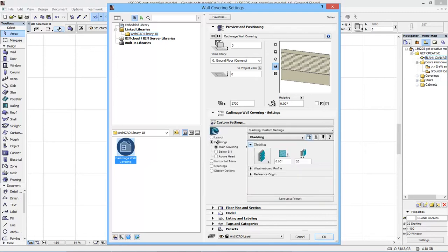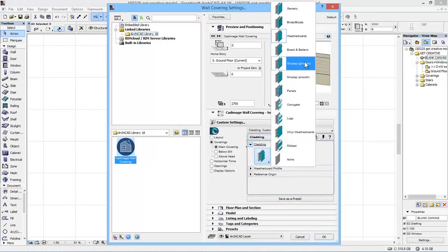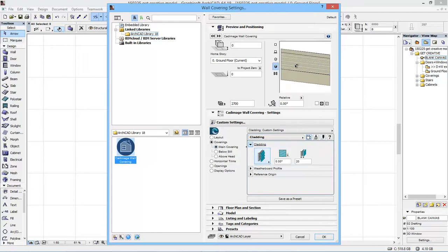If we then look at the coverings themselves, this now is split into 3 areas. There's also 2 settings in here. There's the cladding, and then there's the vertical trims we can apply with it. So we'll take the main covering first, and I think what we'll have with that is a little bit of grooved shiplap. This then has an option to set a rotation and offset, so we'll leave that as 0.